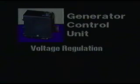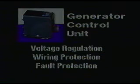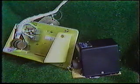The brains of the generator circuit is the generator control unit. This small black box incorporates the functions of voltage regulation, circuit and airframe wiring protection, and other critical functions. The generator control unit also contains fault protection circuitry, nearly identical to that used in the battery fault system. There are two generator control units, one for each generator installed in the aircraft.